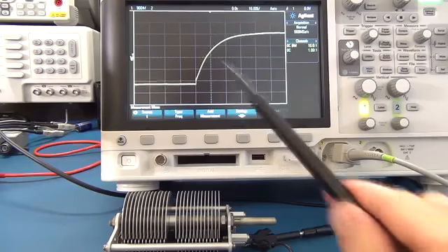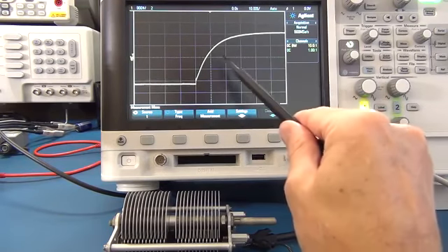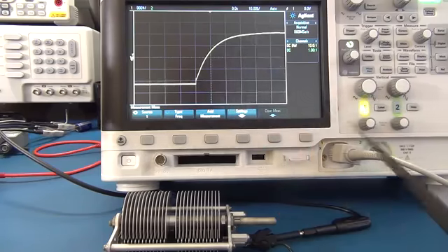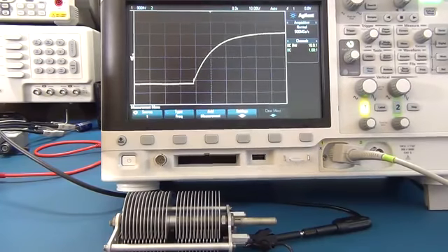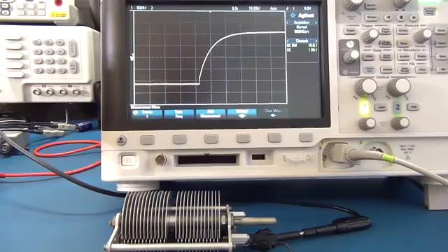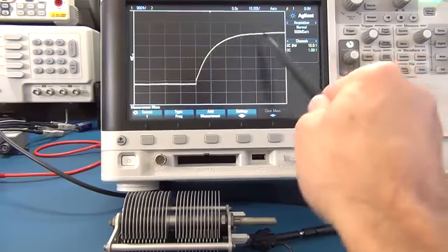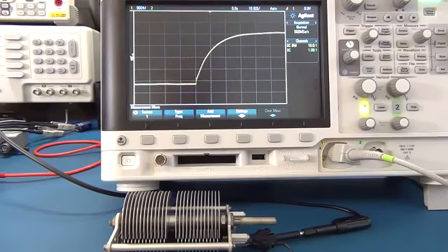Now if I go and adjust the resistance, remember, if I increase the resistance, you're going to get more of a slope because it's taking longer to charge. So I'll just do that. If I go between the two extremes on the one resistor setting, you can see how the slope of the wave changes. Now I've dialed in, just for the purpose of this exercise, 146k. So 146k, and then we get that slope.